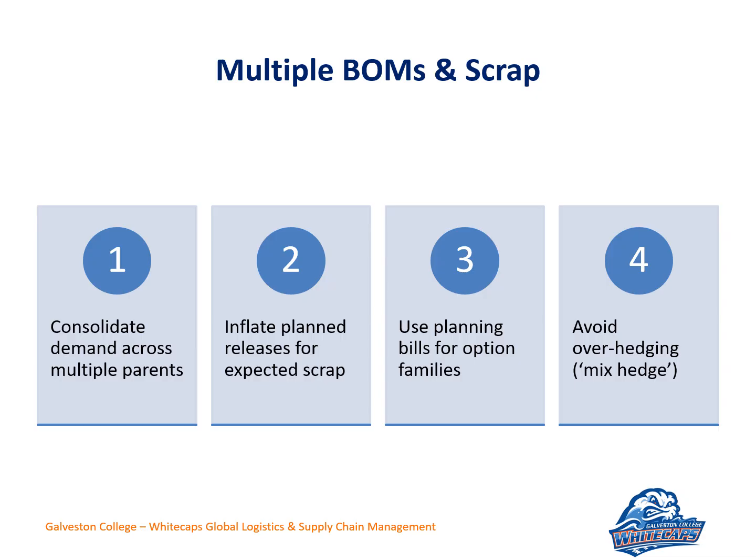Scrap. I may have made a Freudian slip right there. But scrap, because you need to know what your scrap is expected to be on a product, right? I've seen when we had an expected 7% scrap rate on a certain type of material. And I was like, okay, good. So when we planned purchasing, we planned buys, we planned builds, we built that in. And whenever we saw an outlier where it went above that, we immediately investigated because we were planning for a certain percentage of scrap.